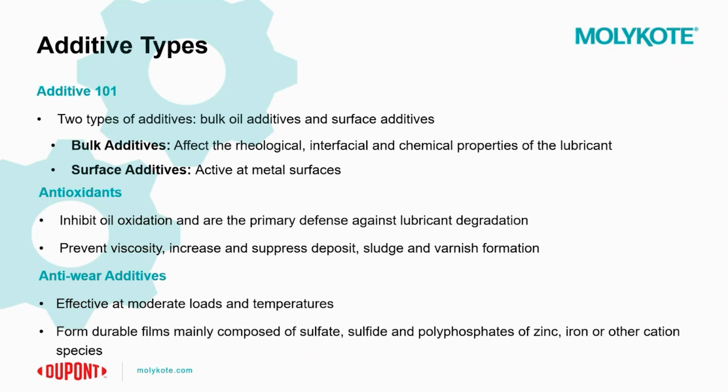In contrast, you could use extreme pressure additives where you have essentially very highly loaded conditions in order to prevent welding of parts. So typically you see extreme pressure additives as either sulfur-based or molybdenum-based, and typically these extreme pressure additives contain sulfur compounds, molybdenum derivatives, and chlorine compounds. And the primary difference between the different types of extreme pressure additives is essentially the activation temperature. So again, it's critical to consider the environment of the application when considering the type of additive that's being used.